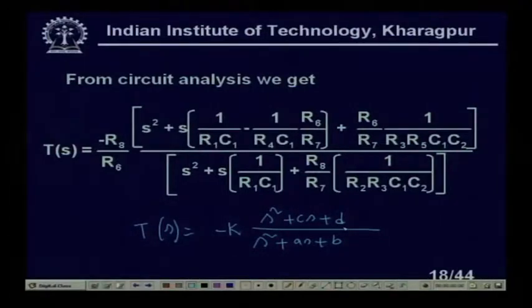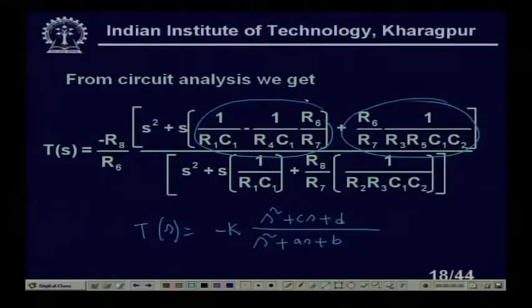For this reason you can see these values, R8 and these components, we can realize by some resistances and capacitances. So, if I purposefully make that portion 0, obviously I can get it. Suppose if I make C and D 0, it will be a high pass structure, right. Similarly, if I make R6 infinite, in that case I can make it a low pass or band pass structure, like that it goes, right. So, with this type of structure obviously I can generate any filter function.